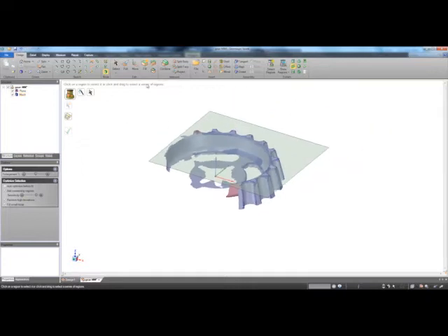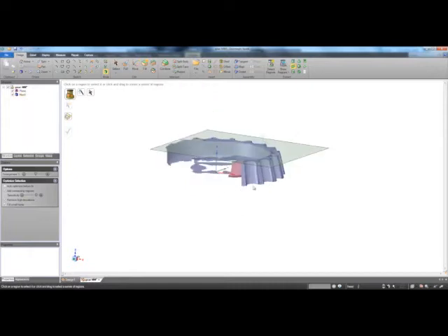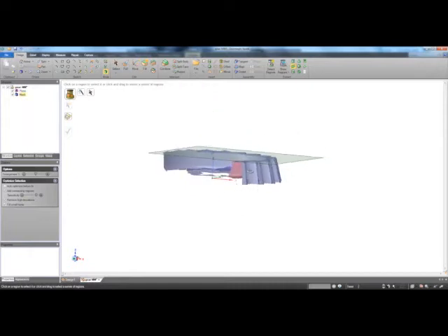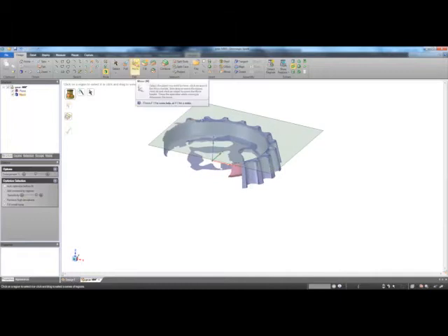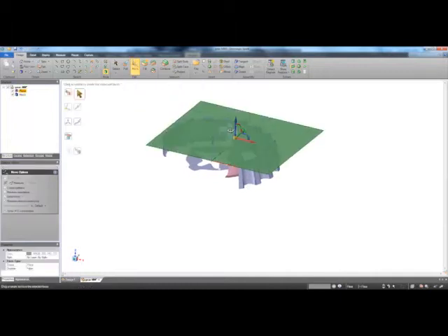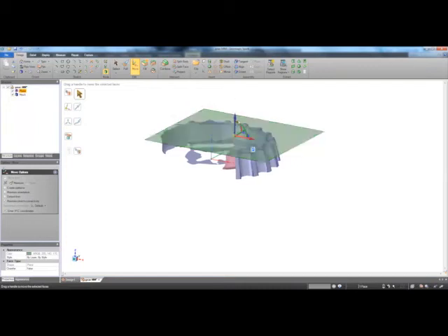The next thing I'll show is the ability to move that plane or make a copy of it to use as, I guess, the base of this gear. So if I go up to Move and select this plane, you'll see a little XYZ widget show up with some rotation tools and dragging as well. If I hold down Control and the left mouse button on the direction I want to move this plane, it actually makes a copy of it.